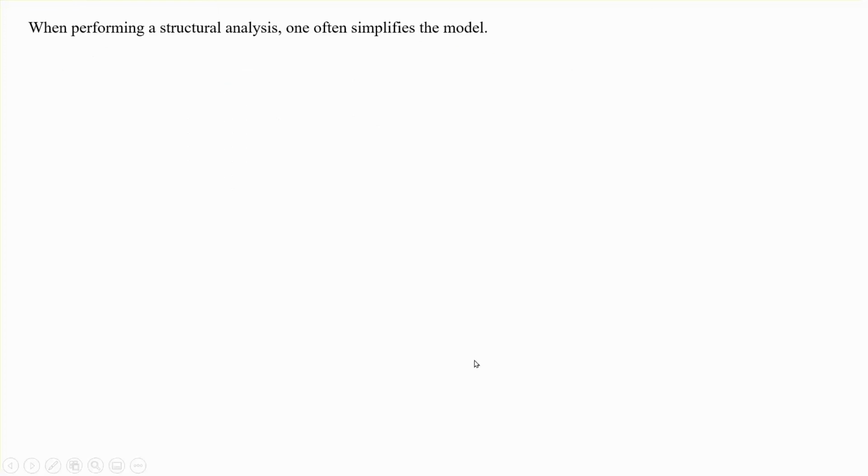Now, I will be doing this problem two different ways. One is the standard process of creating the geometry exactly as it is, and then meshing it and loading it. And then after I do that, I will come back and repeat the same problem, except that the geometry that you saw, a block with the central hole, I'll put some fillets there.